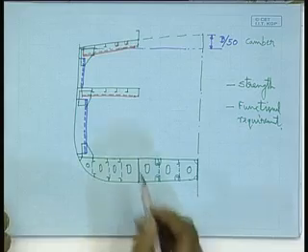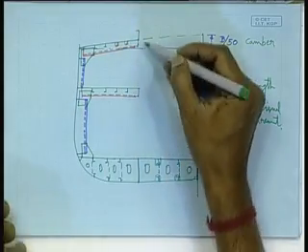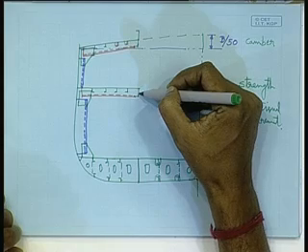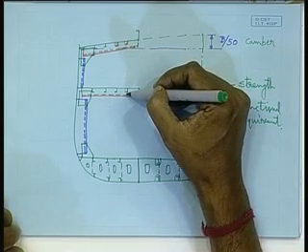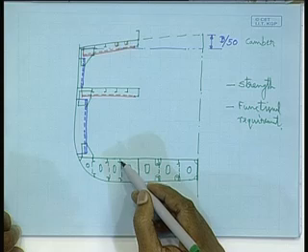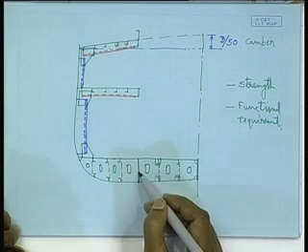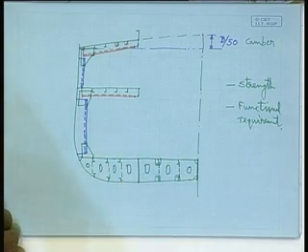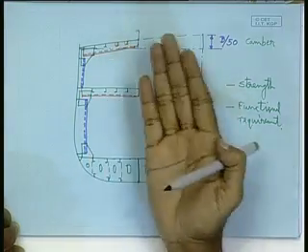What are the members? Well, the shell itself, then the hatch side girders, deck longitudinals, inner bottom longitudinal, bottom shell longitudinal, center girder, side girder. All these are longitudinal members, and longitudinal members contribute towards longitudinal strength. So, we have sufficient of them, and also we have the transverse members in the transverse plane.